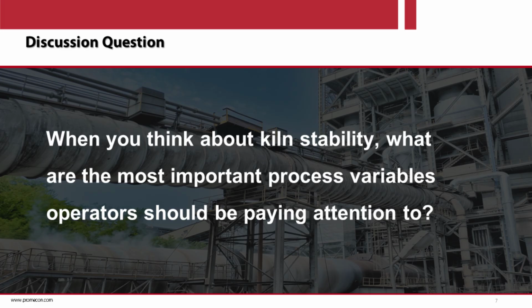And if you are able to measure the gas flow, you will see that the flow will stay constant, for instance, for a constant opening of the damper at the TAD. And you will see that your draft static pressure will vary, let's say from 80 millimeter water column to, let's say, 60.